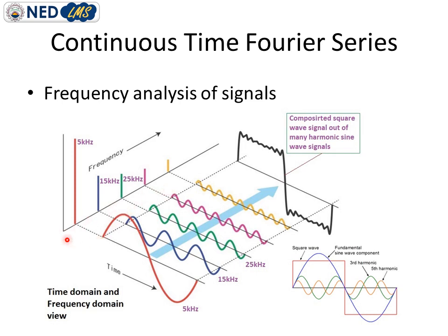This is the frequency axis, frequency is increasing this way, this is 0 frequency, then 1, 2, 3, 4, 5, and this is exactly 5 kilohertz, and you are getting a spectral line at 5 kilohertz, and its strength is more as compared to all the other spectral lines, because this wave is contributing the most towards the shape of the square waveform.